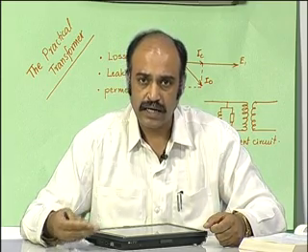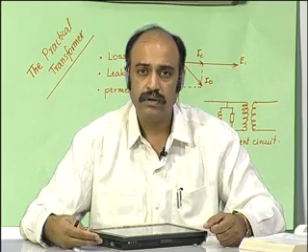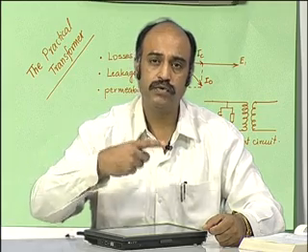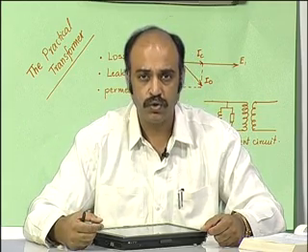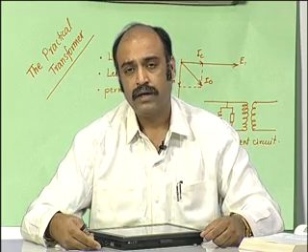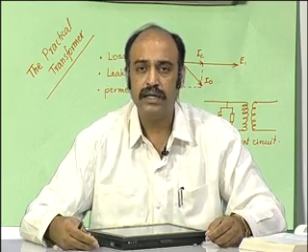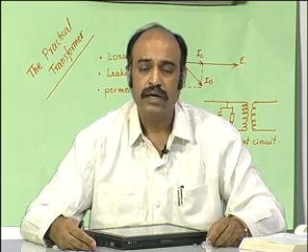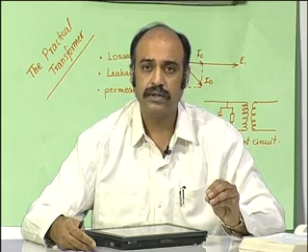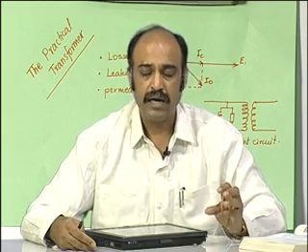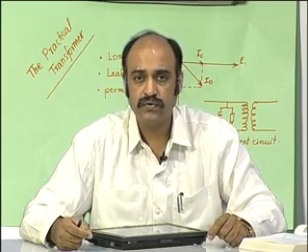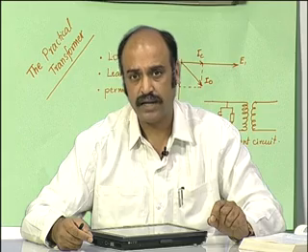Because whether it is the reactive load or the active load, the transformer has to undergo so many cycles, which means so many traversals of the hysteresis loop, and also the eddy currents in the transformer do not distinguish between the reactive load and the active load. Therefore, the heating in the transformer is related to the VA or the apparent power that is flowing through the transformer, and therefore, the nameplates of the transformers are rated in terms of VA rather than watts.